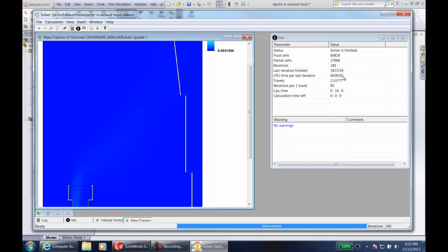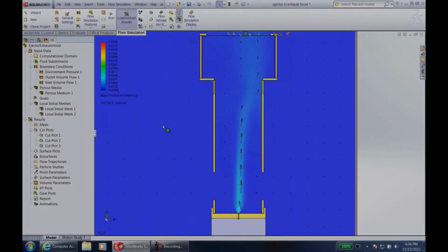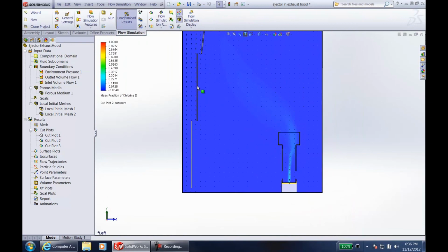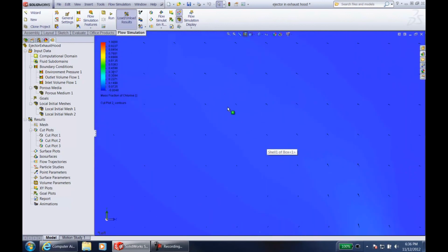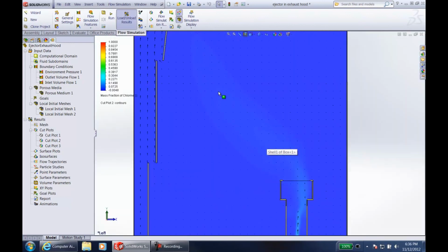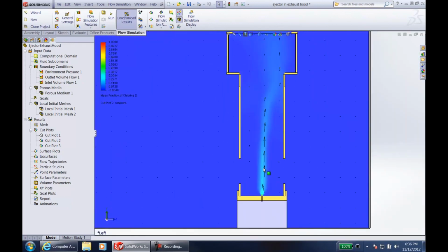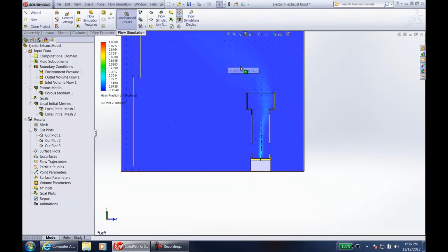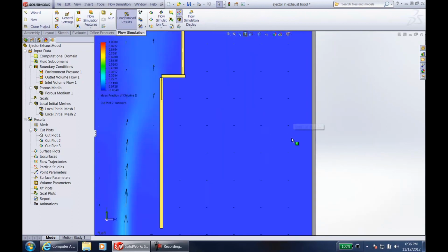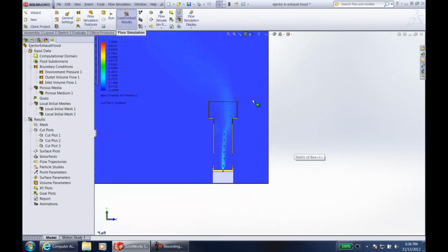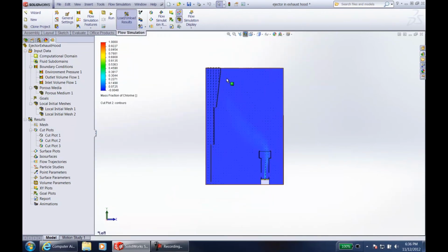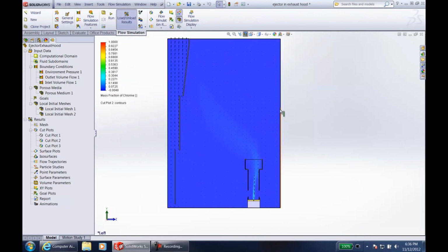And we look at the preview window here. So I have two cut plots being displayed, one for the concentration contours and one for the velocity vectors. And you see the velocity vectors kind of aligning themselves with the airflow and the chlorine flow. The air comes in here at a small velocity. Keep in mind, it's probably a large flow rate since we're pumping in 1,000 cubic feet per minute over a large surface area right here.